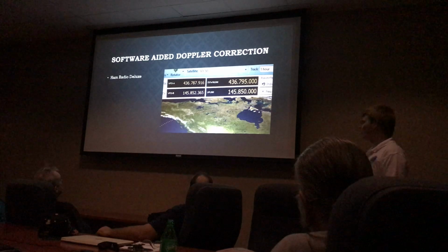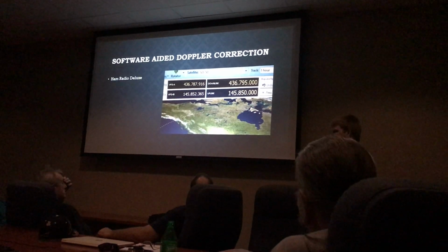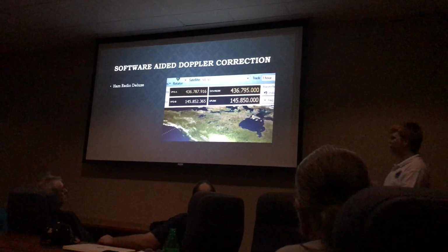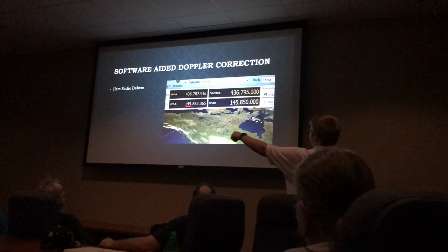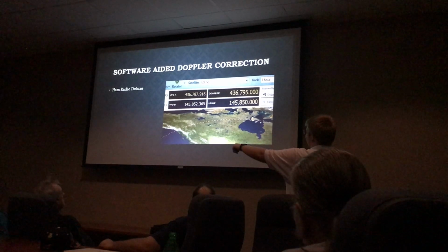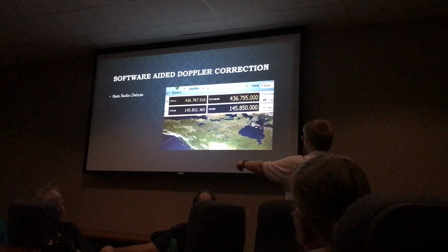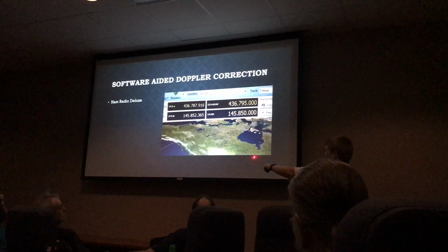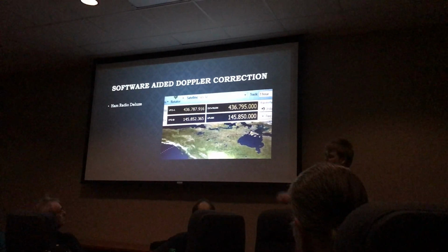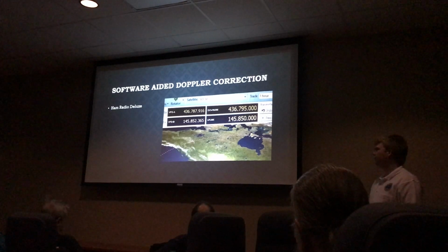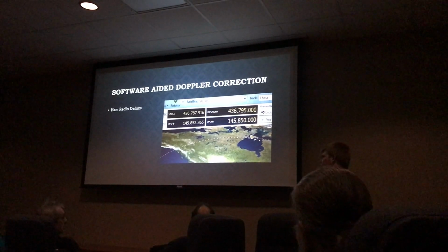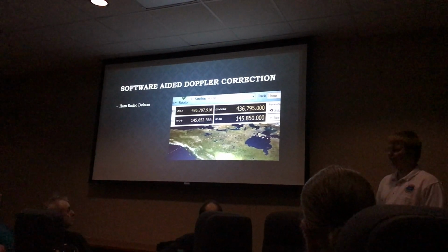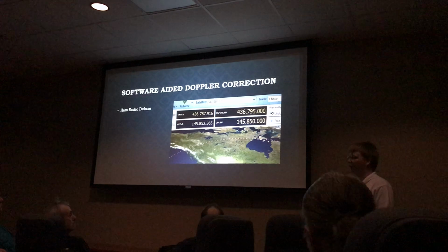And then more so it's about lining up your transmission frequency. If you take the bandwidth and spread it across here, and you're transmitting over here but you're coming down over here, usually it's easier to find yourself where you're transmitting, and make sure you're in the same section. Usually you need a duplex radio to be able to do that. I don't use a duplex radio, I use a simplex radio, and it works fine.